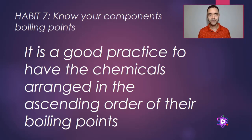In this case, I verified that it's not possible to remove nitrogen from the biomethane even though I use cryogenic temperature, if I want to have methane as product, because the methane will liquefy or condense first than nitrogen, and based on that I will not produce a gas rich or without the nitrogen.